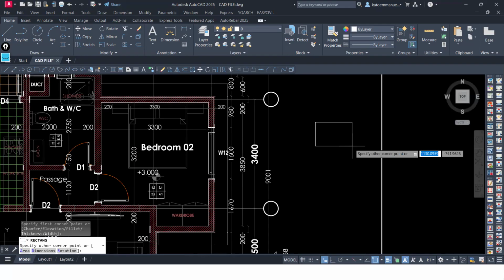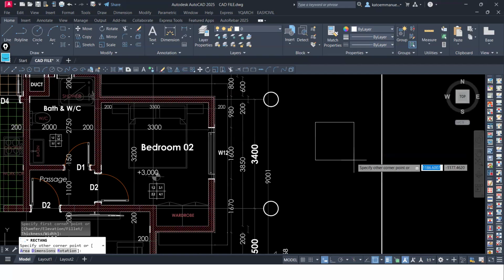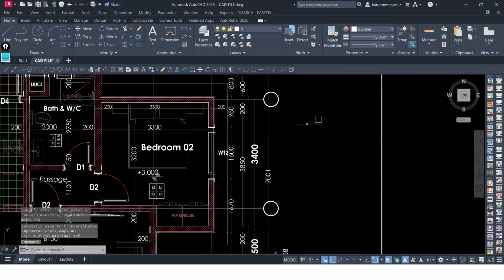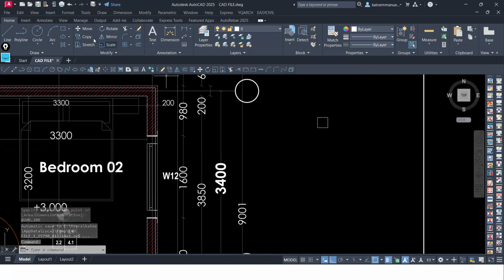There is a limit. We don't go below 200. It is better you have a bigger column which is met by the wall than having a bigger wall meeting on a smaller column. You get it? So let's have 200 now. I'll press tab by 200 and create this. It should be a restricted rectangle.